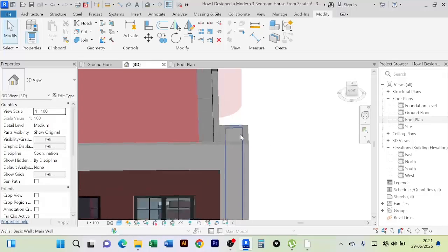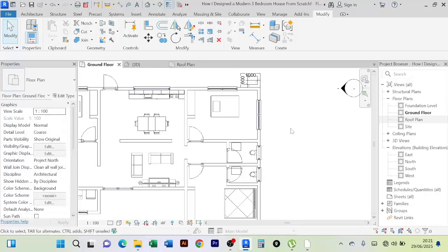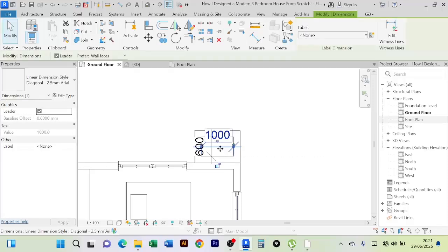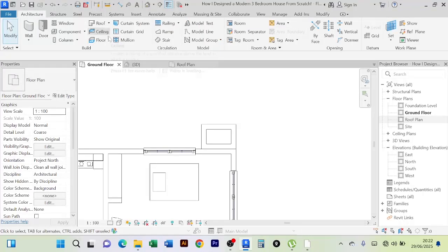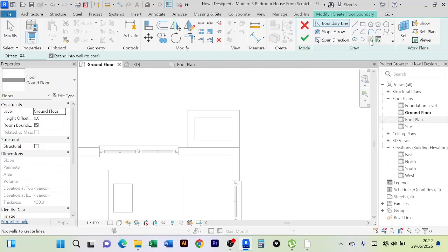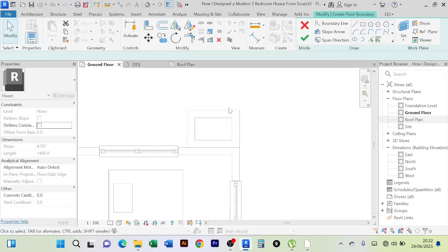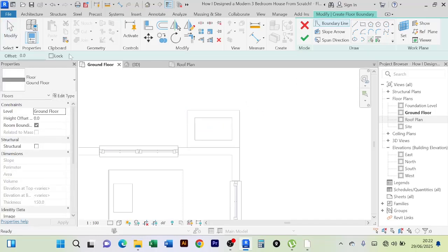So this one has to be covered because it is open really. So I'm going to delete these dimension lines. So you have to cover it with a floor. So I'll come to texture. I'm looking for a floor. I'll use a texture floor. Then of course we shall pick lines. You can even let's say we are going to offset. You pick line, you come to the offset. We shall offset let's say 100, just like this.